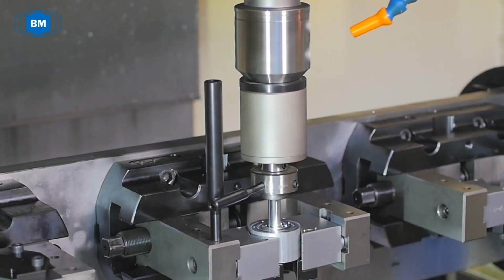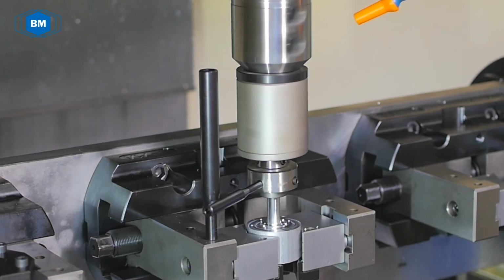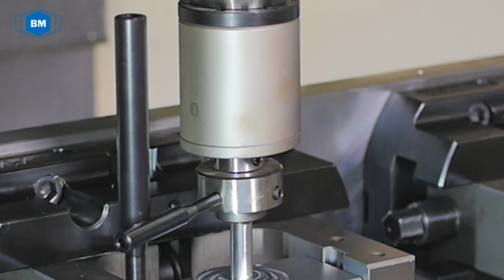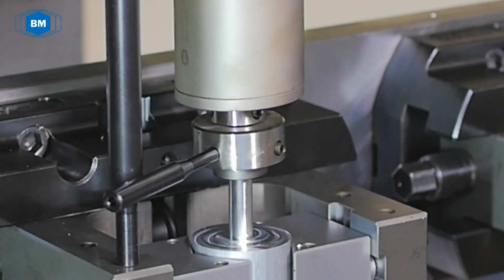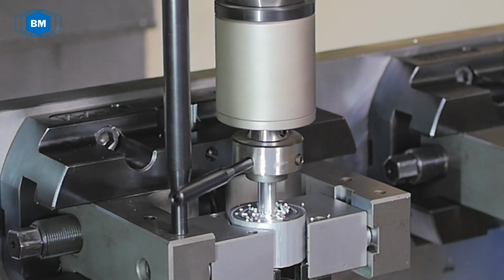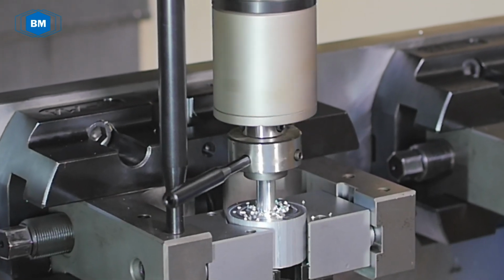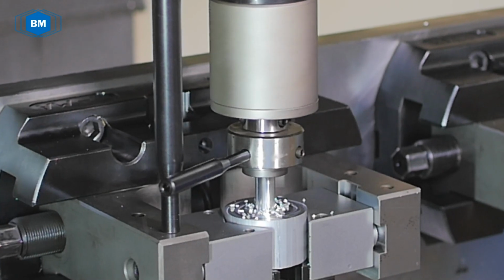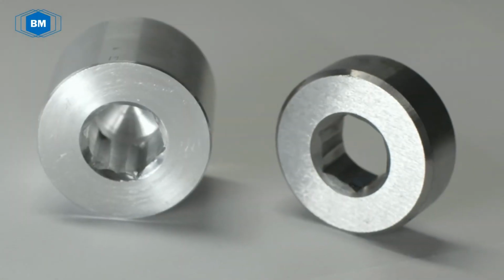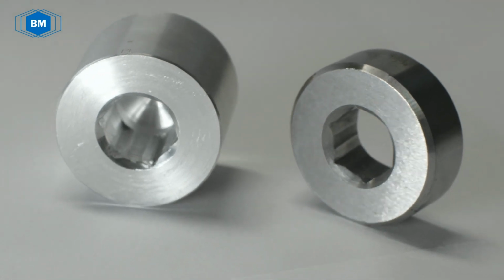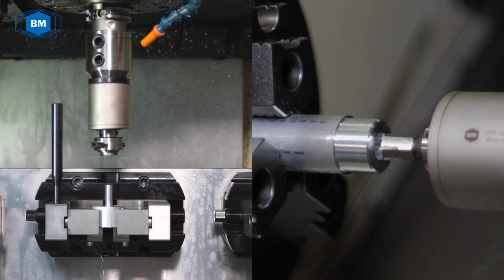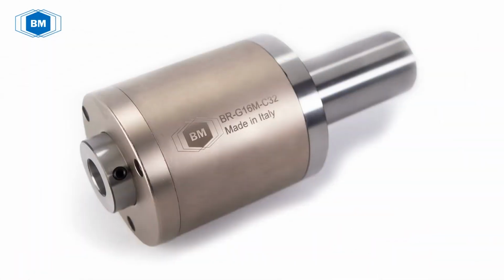The machining center spindle starts, and the Brighetti broaching tool starts spinning. Upon contact, the broach ceases to rotate while the broach body continues to rotate, and thanks to the pendulum oscillatory movement impressed on the broach by the broaching tool, and the vertical feed impressed by the machine tool, you get the desired figure. Naturally, these two different figures, polygonal in blind or through hole and external polygonal, can be made indifferently, exchanging their respective operating machines.